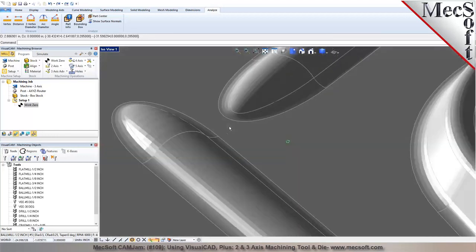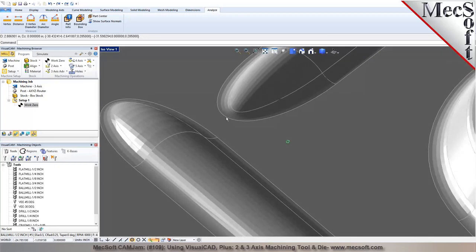Okay. Right in here. Can we figure out the width here? Absolutely. So what I'm going to use is a tool called distance, minimum distance between 2 points. And I can use what is called a near object snap. So snap to 2 points that are close enough right here, 1 and 2. So that's about 0.189. So if you have a 3/16 bit, you might be able to get in there, or maybe you can go slightly smaller than that.